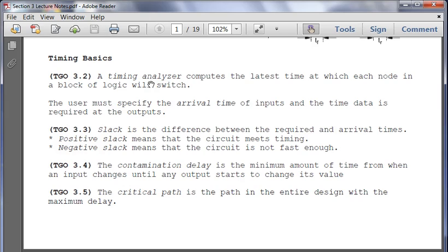There's a type of adder, when you're finishing writing that, called a carry select adder that tries to address this issue by cutting the runtime from big O of n to big O of n over 2 by doing the first set of carries. And then they actually have two second adders. They have 16 1-bit adders, and then they have 32 in the second half. One of them starts with a carry in of 0, the other one starts with a carry in of 1.